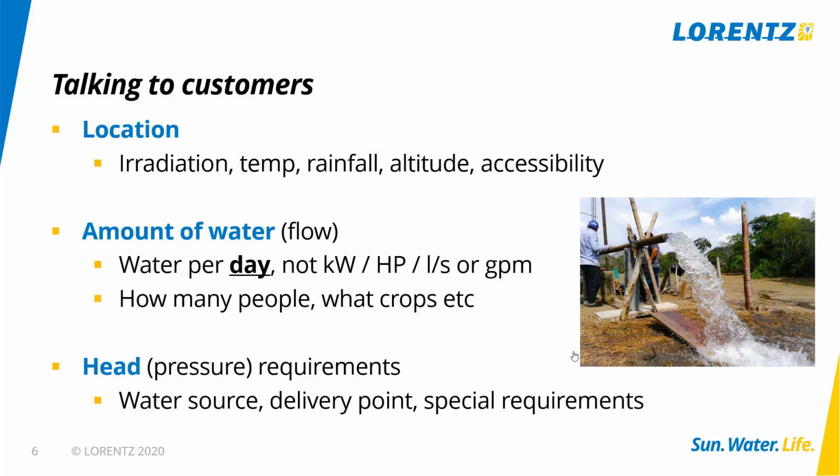So this means we can very accurately model how much sun is there likely to be on an average beginning of May day, how much solar energy is coming. So then we can calculate how much electrical energy we can get, and then we can take this through the model. So location is really important. It's good to know the location. We don't have to be absolutely accurate down to the meter. We need to know which area it is in, so we can allow the software to pick the right data up.